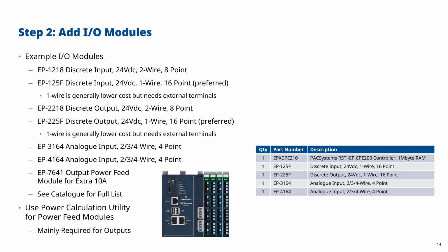But there's your simultaneity factor. It's 50%. Only half the outputs are on at any one time. And it might be your solenoid isn't half an amp, maybe it's only 1/4 of an amp. But assuming 4 amps per module, you can see there that, depending on the number of points, you might say, okay, I'm going to have 128 outputs. You might say that my simultaneity factor is 50%. So that means now I've got 64 outputs. You might say they're only running at 0.25 amps each. So that would bring you down to 32 amps. So 10 amps isn't enough.